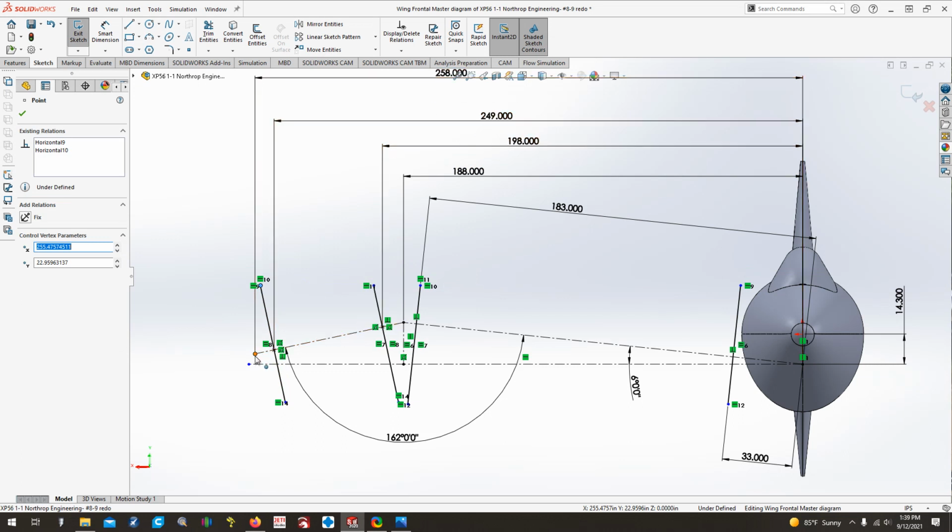There's another one here at the end of it. That's a 258-inch theoretical wing station line, which would be the very tip of the physical wing panel, if it wasn't chopped off for the actual wingtip. And then I did the same thing here for the 183-inch station on the wing, and then there's nothing here at the wing center, the root at the center line of the fuselage, because in building a full-scale airplane, they don't have a rib here. The wing stops here and they have some structure that bolts the wing in.